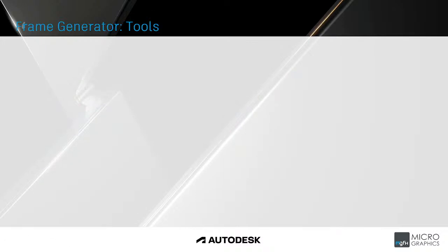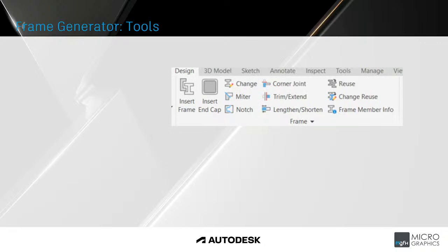So let's look at some of the frame generator tools that are available. As you can see, you've got your insert frame, insert end cap, your miter, your notch, your corner joints. So these are some of the tools you get. First we've got the insert end cap. This places end caps on the selected frame members. Next you've got miter your corners. Miter your corners applies miter cuts as end treatments between frame members. So that basically cuts your corners.